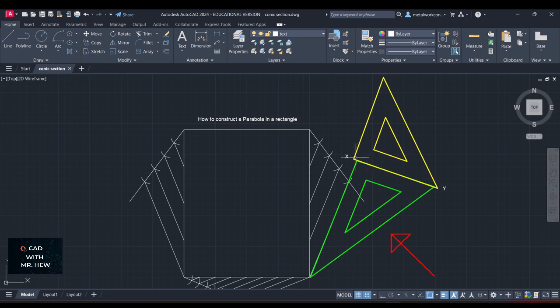And you would align it to this edge X, Y. So you would use your right hand, if you're right-handed, to hold down the 45-degree set square, the yellow set square. And then you would align the 30-60 set square, the green set square in our video, to the line that you want.